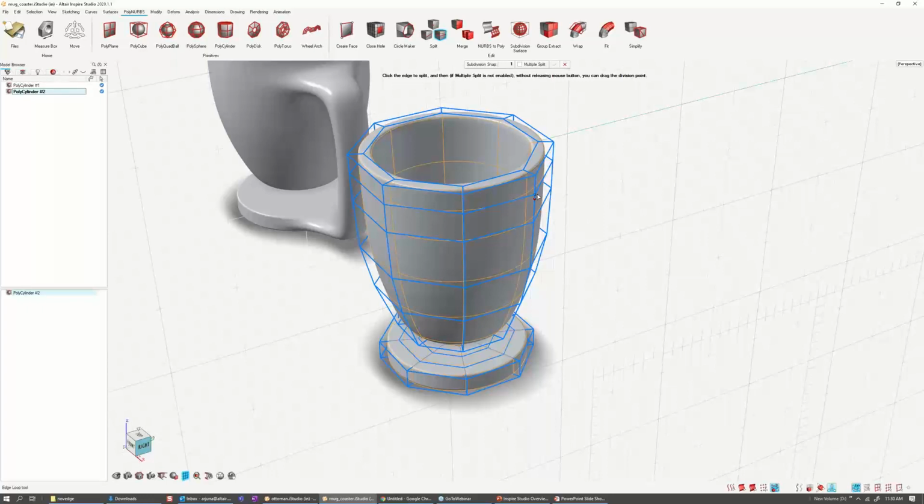And now I can create the feature that I was talking about. So here, before I do that, I want to show you, actually, select two faces. So I'm going to select this face, hold Control and select this face. And when I have more than one face selected and you click on this extrude handle, both of them should be extruded. So let's extrude it and see what happens. Okay, so you see there's something funny happening, which is basically they're going in the opposite direction, which is not what we want. So I'm going to hit done and Control Z to end this.